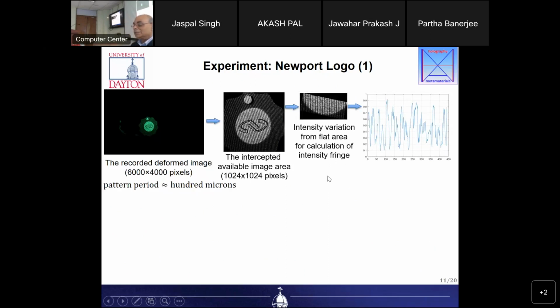Now, this is the simplest kind of fringe, just straight. You can change the angle. If you change the angle, sometimes you'll get better resolution, sometimes less. It just depends on how much of the light is distorted when it goes against these cracks or dents. If you did a more complicated pattern, like a checkerboard pattern, you'd get more information. That's more of a structured light. So you can improve on this; there's a lot of scope to improve. But this was just a demonstration.